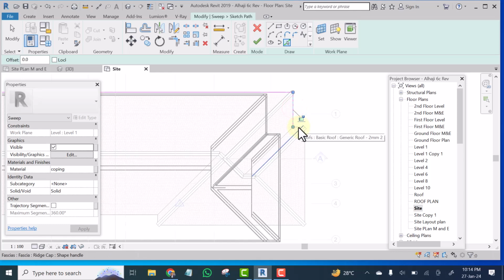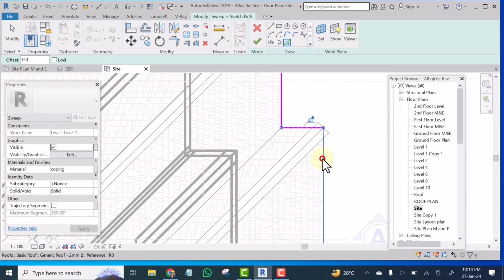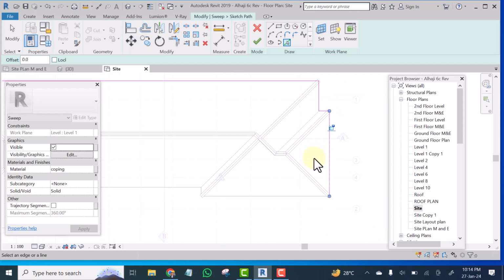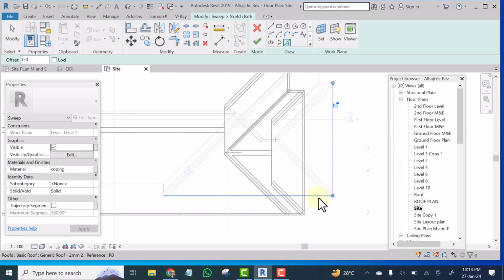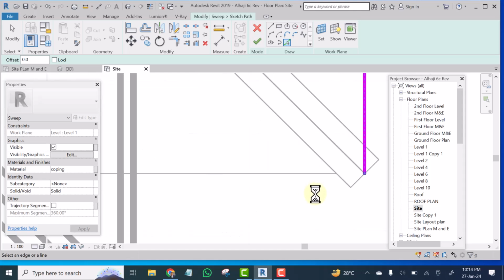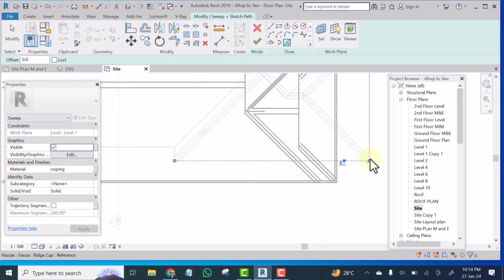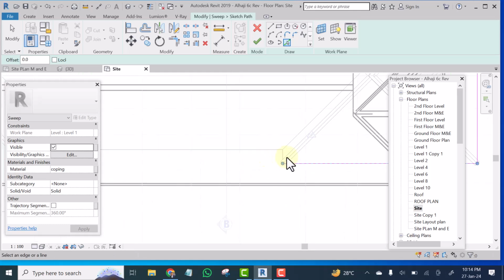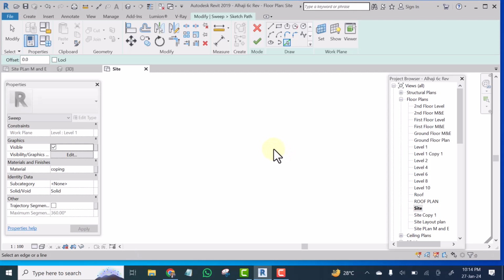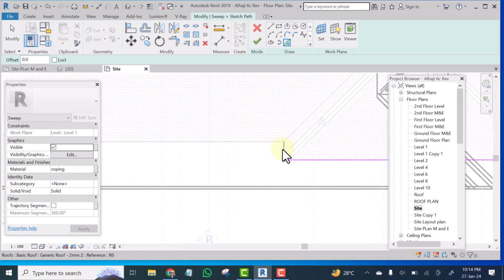All right, so I'm going to pick the outline, and I'll make sure it doesn't intersect itself. At this point you need to make sure it doesn't intersect, and it must be looped. The line should not be in pieces. The line must be completely joined together, so you need to take your time to make sure they join together. It must be looped. That is what it means to be looped.